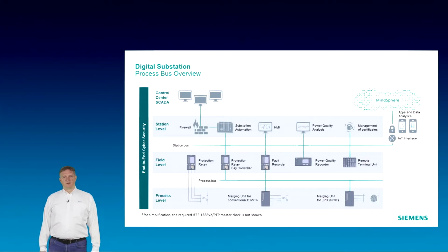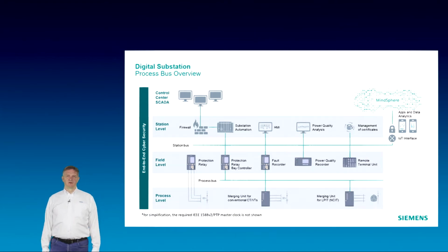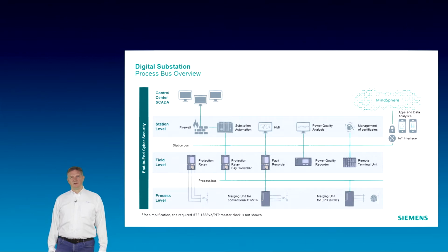What is a Process Bus? It is the digital interface between the process level and the field level. As shown on the left side of the illustration, traditionally the instrument transformers from the process are directly connected to the IEDs of the field level, for example the protection devices.